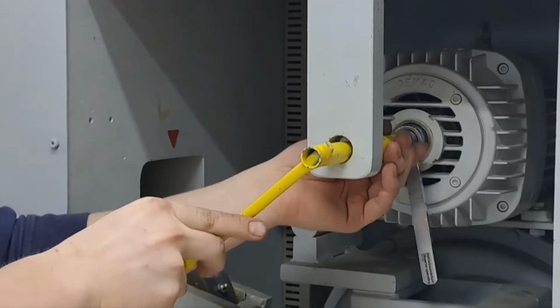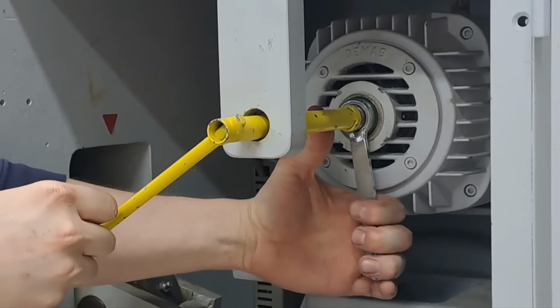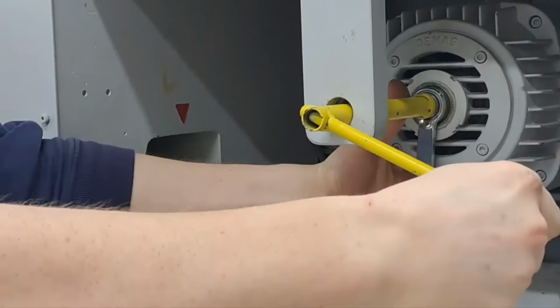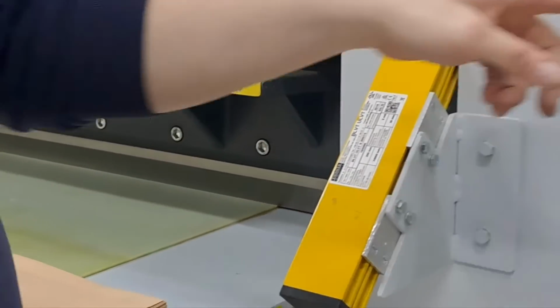Otherwise it will jump out. So with this one here I can release the brake from the motor and then I can turn it by hand. Once we have removed all the screws here, I can release the brake and bring the beam